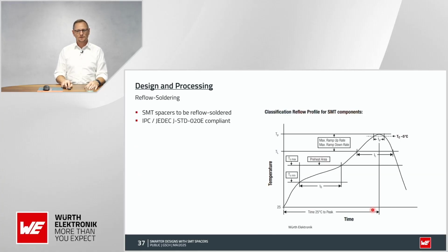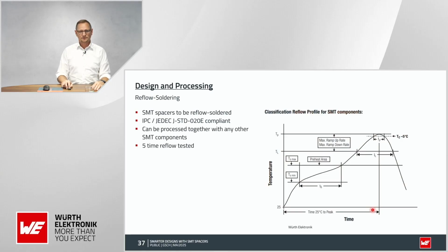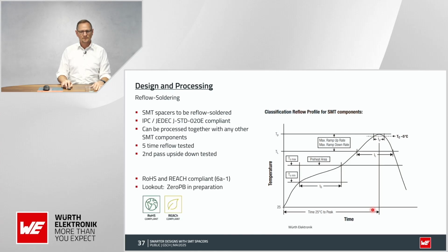So then you can use them in a standard solder profile. You don't need to adjust your typical solder profile too much, and you will end up with good results here. So they can all be processed together with other SMT components. RoHS and REACH compliant?